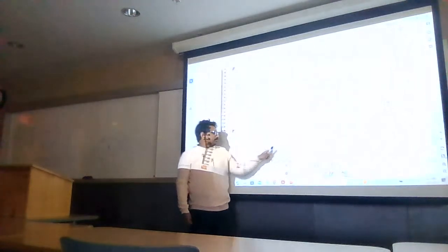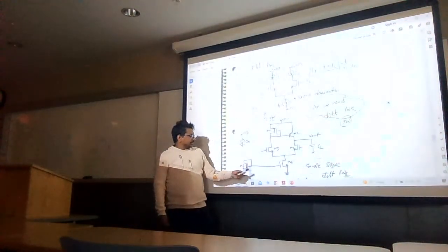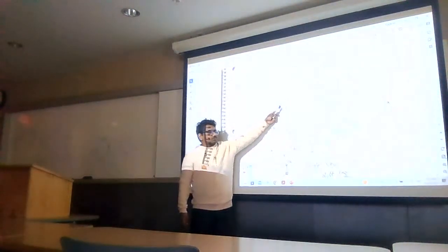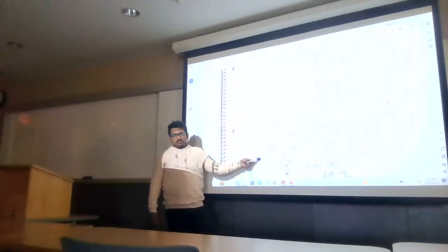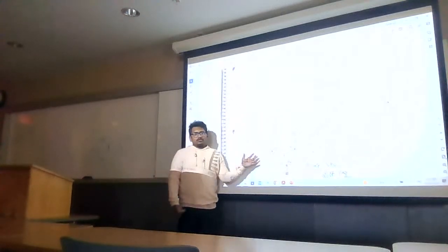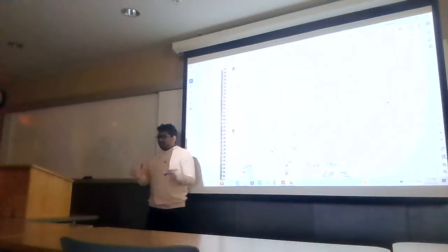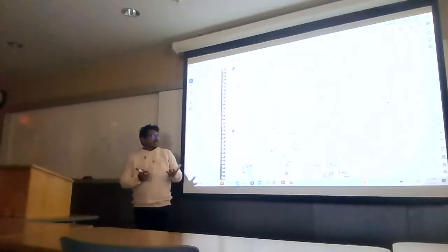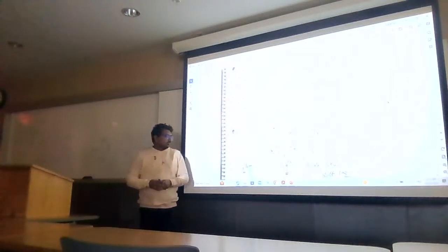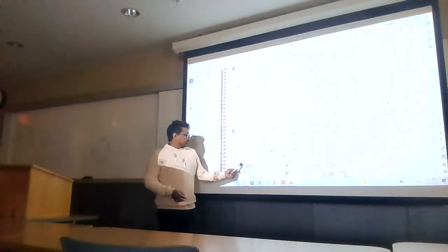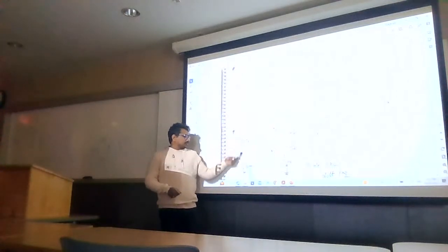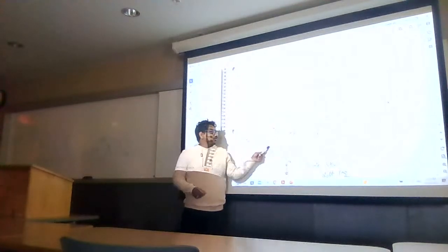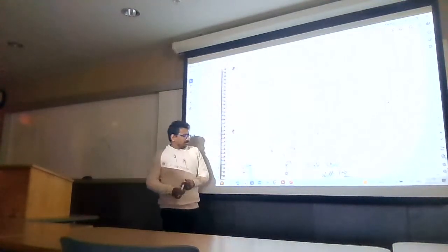And this is my differential pair, M3 and M4. We have to design this one with transistors, meaning we are replacing everything with transistors. Don't worry about the structure, because every company has its own structures. You just have to change some properties and make some improvement in the circuit, that's it. And it is also a current mirror. This is my reference current, it's coming from here, then it is mirroring here, and it goes into these two branches, and that's the output.